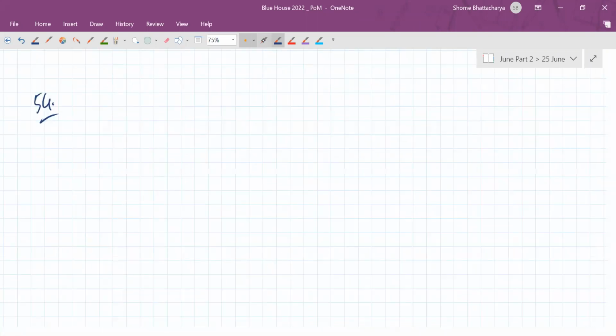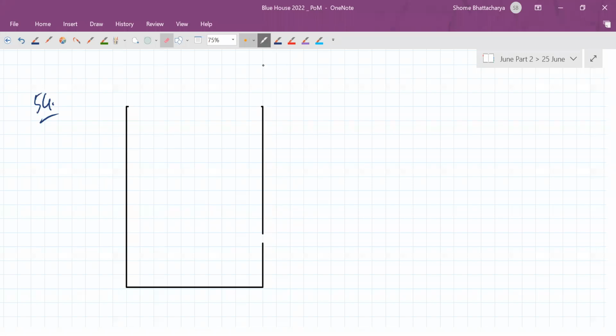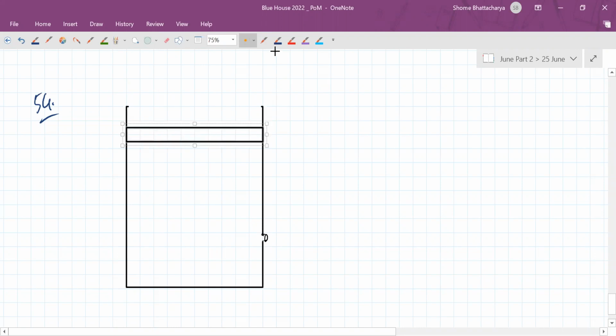Okay, so this is a slight variation of the standard speed of efflux derivation, because in that, what happens at the top surface of the liquid, it's an open surface, so the pressure is equal to atmospheric pressure. But here that will change because there's a piston. So the weight of the piston will contribute to the pressure at the top surface. So this is a piston of mass m, cross-sectional area A. This depth is y.